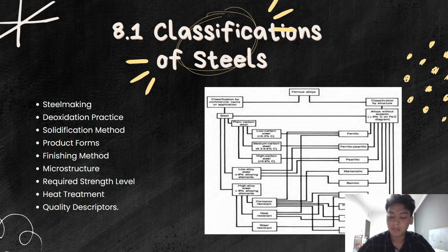After steel is melted and refined, it is then solidified into useful form by various casting methods. On a tonnage basis, most steel is now solidified in continuous casting operations, but casting of steel still involves the original method of solidifying into ingots.